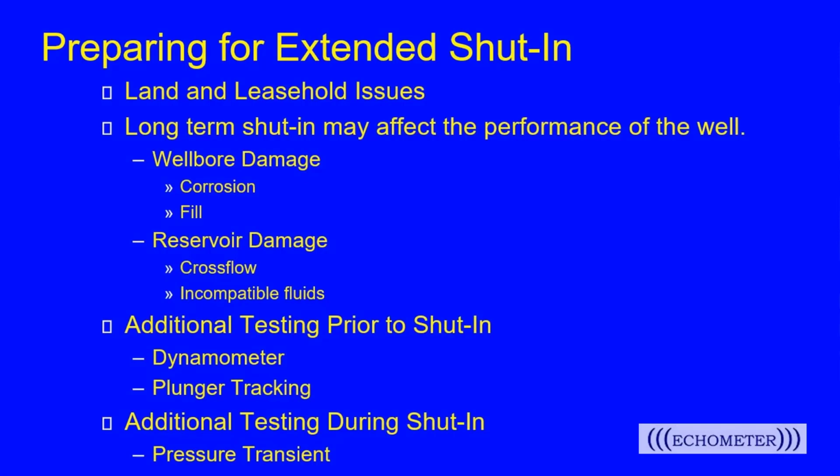We could have some issues with reservoir damage. One thing that can happen on a well that's shut in for an extended period of time is that you may have cross flow. If you have several zones open and you're normally producing where your bottom hole pressure is low, both of the zones will be flowing into the wellbore.